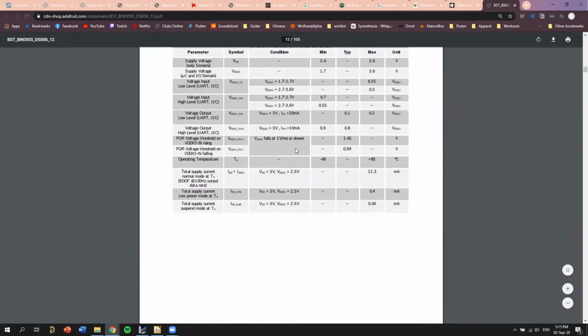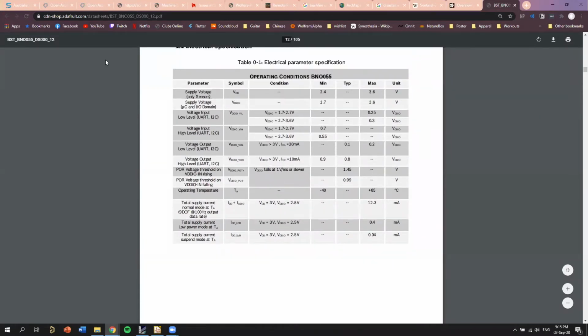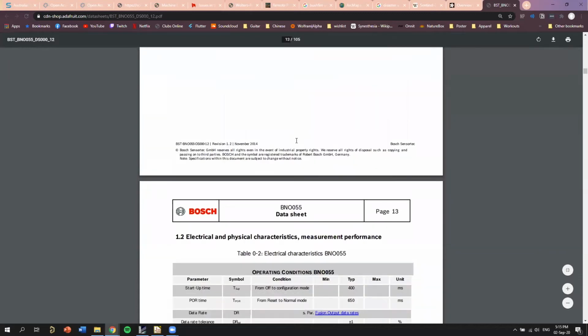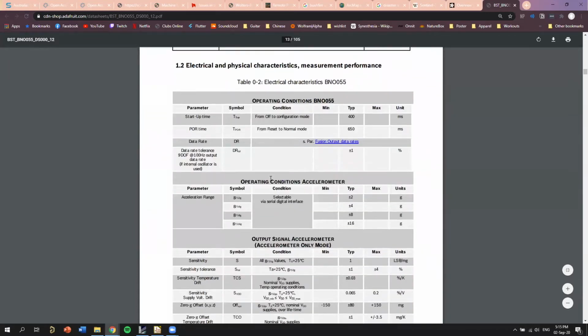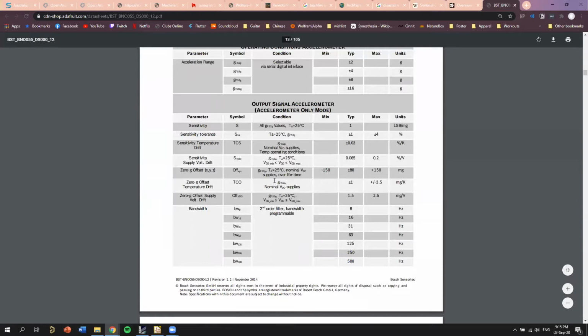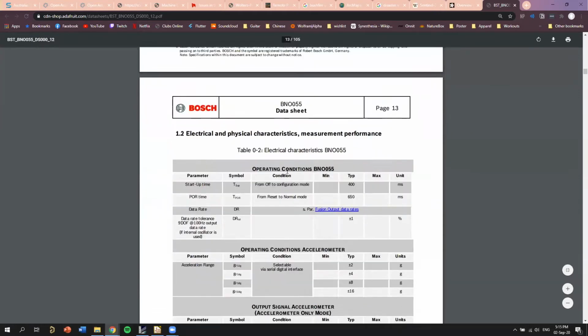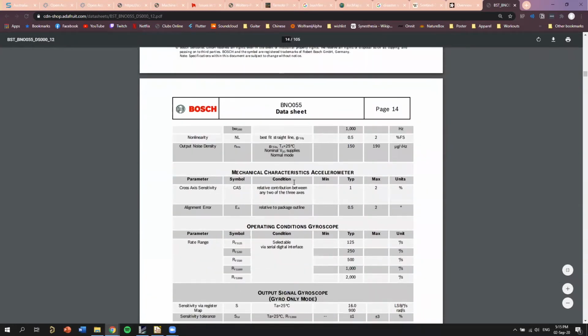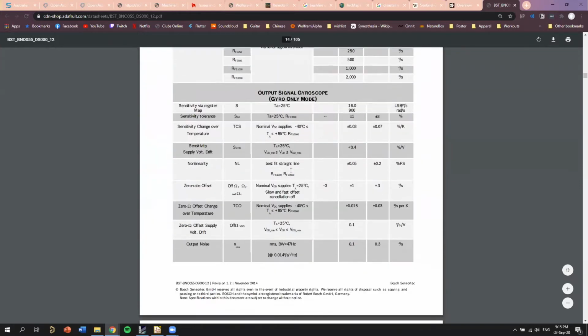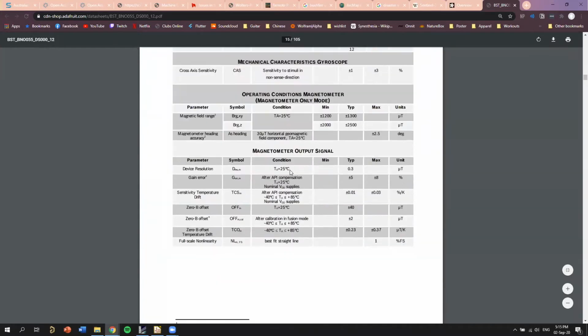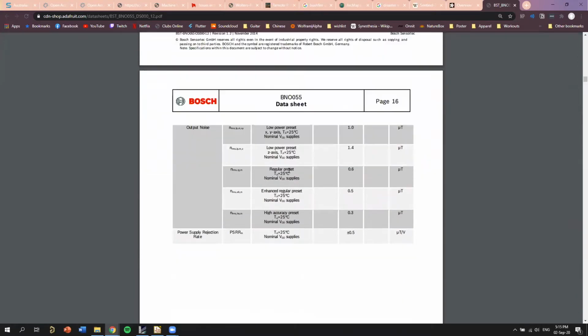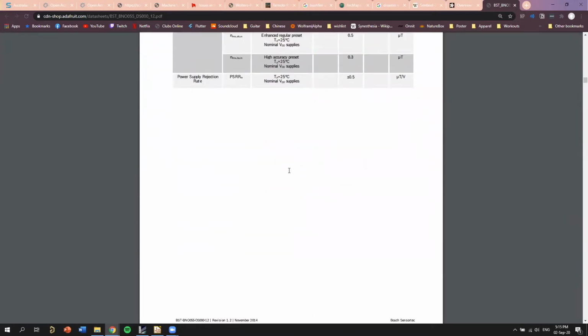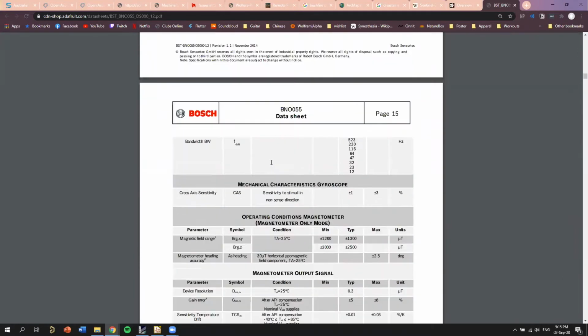So in this case, with this sensor, if you put 5 volts into it, it will probably die, unless we find a maximum. Sometimes they give an absolute maximum rating for different pins, but it might be referring to that there. Let's have a look. Power supply rejection.